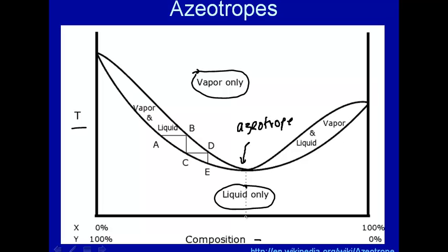So at this particular composition, you'll get a mixture where there's no separation between the dew point line and the boiling point line. What does that mean practically? Well, let's say we start at this particular composition and we increase the temperature of the liquid, and finally we get to boil. We collect the vapor. We then condense the vapor into a liquid. We then boil that again, condense and boil. But what you see here is that you're never going to get a pure substance.